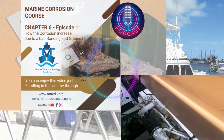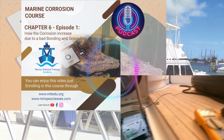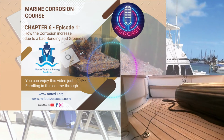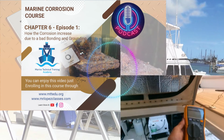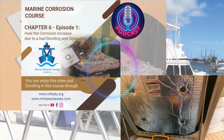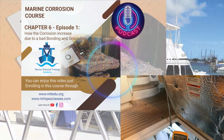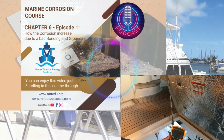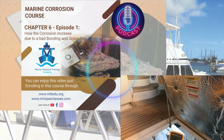The negative bus bar is a critical element in the installation of electronics. We need to verify that this negative bus bar is properly installed, is properly insulated, is properly bolted, and the terminals over there are properly crimped according with the procedure that I explained in previous episodes.